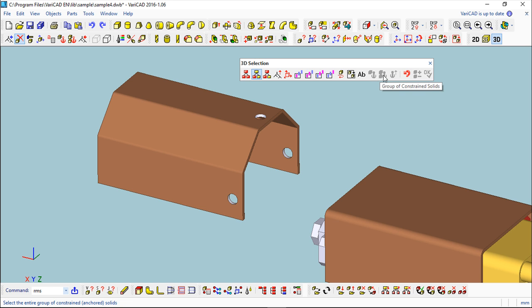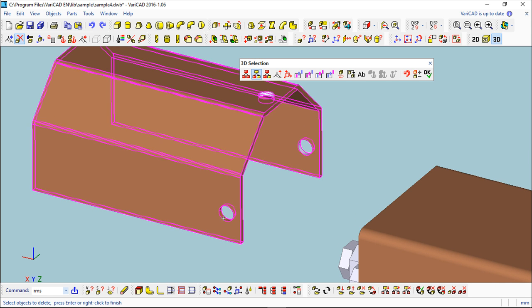Constrain elements or constrain solids is another topic that we will see, and also a schematic for the constraints. This is to undo the selection, and this is the select, which we already saw in some particular uses on the 2D side, and this is to confirm the selection done. So in this particular case, we were seeing the possibility to edit the solid by deleting a component. I choose one single element, select this one, just do the OK, and it was edited.